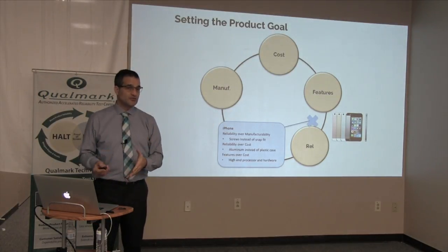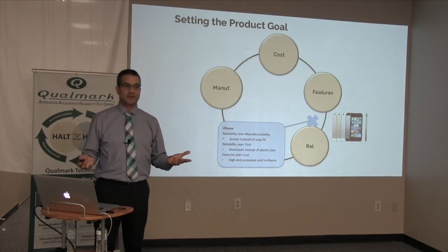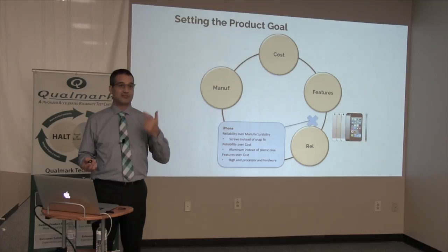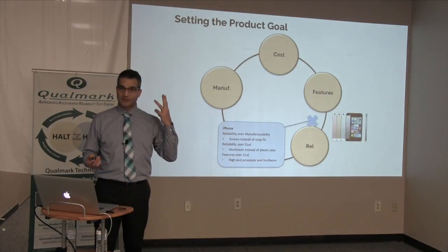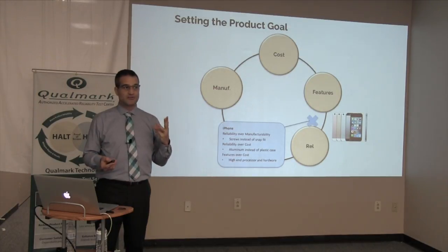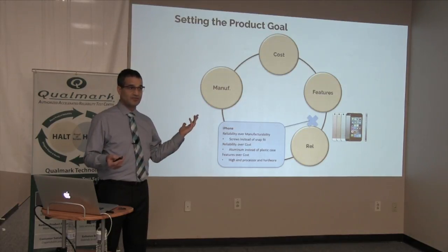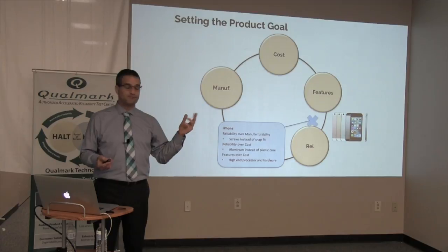The decision for screws, instead of snap fit, is a big no-no for design for manufacturing. When you want to design for manufacturing, you want fewer parts, fewer steps, less variability. Screws are against all those things. But if you've decided your use case profile includes this thing being dropped every so often by the customer, screws are going to hold it together better.